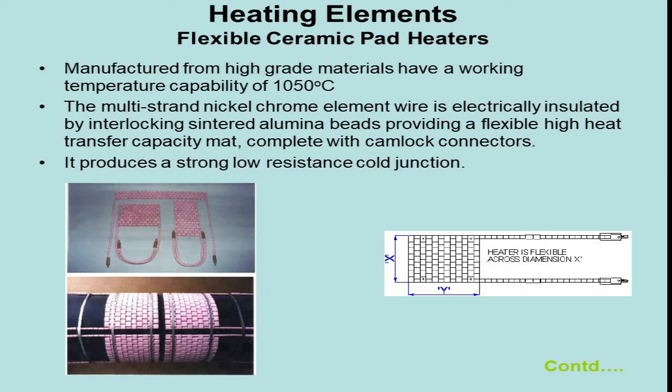Flexible ceramic pad heaters, manufactured from high-grade materials, have a working temperature capability of 1050 centigrade. The multi-strand nickel-chrome element wire is electrically insulated by interlocking sintered alumina beads, providing a flexible high heat transfer capacity mat, complete with camlock connectors. It produces a strong low-resistance cold junction.